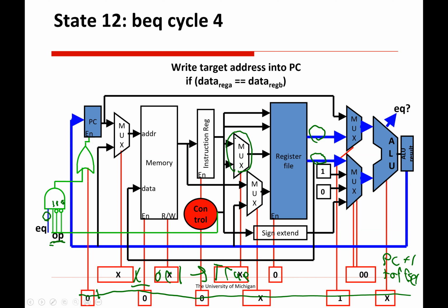This mux here, this top one is the destination register index. And the reason we have two inputs there is because in the ISA for LC2K, there are two different spots that can indicate which one is the destination register. For ANDs and NORs, it's the last register, bits 0 through 2. And then load word is the weird one that has register B as the target register. So this bottom one is for ANDs and NORs. This top one is for load words.